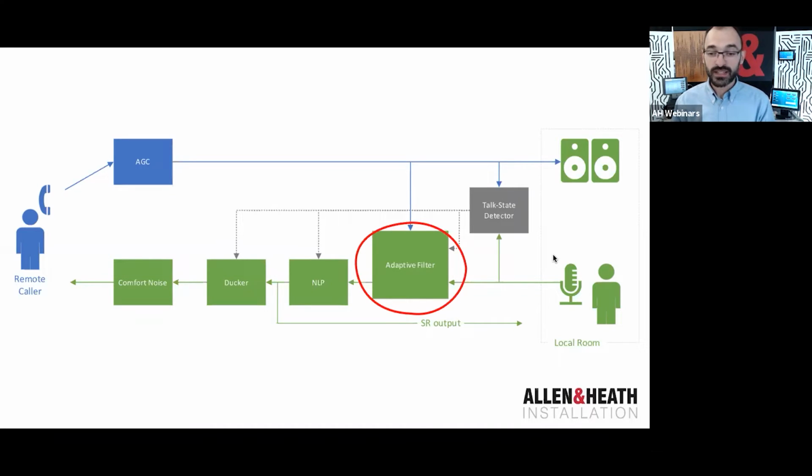algorithm, and the DSP engineers really have to use all of the possible tricks up their sleeves to make the adaptive filter work. For example, the adaptive filter is typically an FIR filter, so finite impulse response. And as the system impulse response increases in length, the filter length must also increase to match that. So for a typical adaptive filter length of, say, over 100 milliseconds for an AEC processor, the computing power required to implement a convolutional filter of that size is very large.